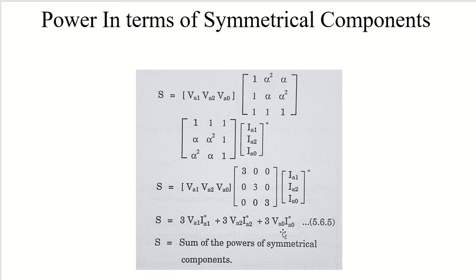So what does it indicate? It indicates that symmetrical components transformation is power invariant. So the sum of the power of the three symmetrical component systems will equal the three phase power. So based on the symmetrical components, you can also determine the three phase power.